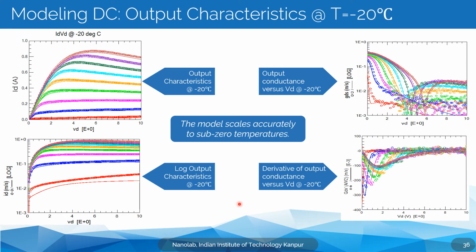Now what we saw till now was the extraction of this power device at room temperature. In order to move forward, we need to extract the parameters for different temperatures, and for this we use the parameters we talked about earlier when we discussed temperature scaling of the core model. So basically 3 different parameters: one is the parameter for Voff, the other one for mobility, and the third one is for saturation velocity. Using those 3 temperature dependence parameters, we can then extract the